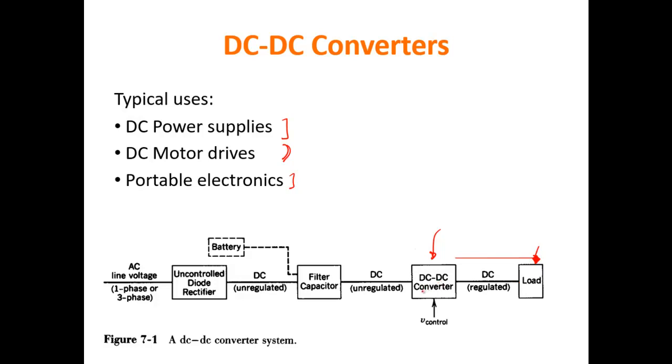Let's say going upward, we can obtain as an input to the DC-DC converter a battery, as in the example that I've shown before. And in the case of a battery, you typically have a filter capacitor in parallel to the battery.